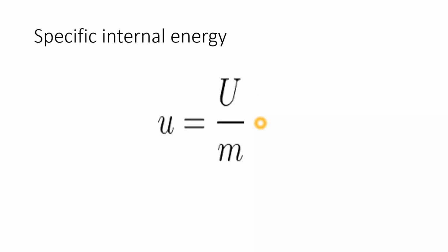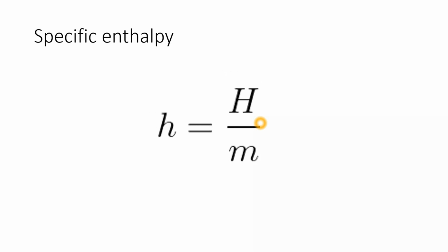Next, specific enthalpy. It is also independent of the mass, since if we take a larger amount, then enthalpy is also higher, that means the ratio will be fixed, so specific enthalpy is also an intensive property. Whenever there is any ratio, generally they are intensive properties. And remember one more thing, whenever we divide an extensive property with an extensive property, the answer will be intensive.